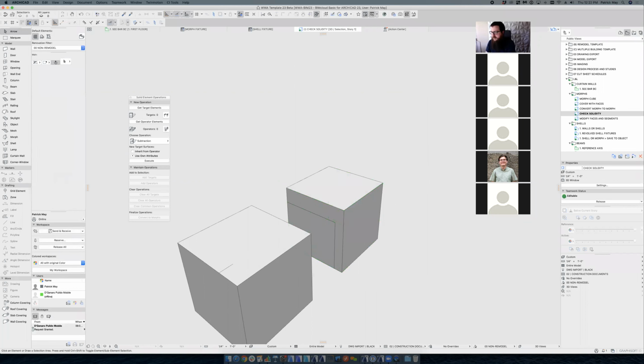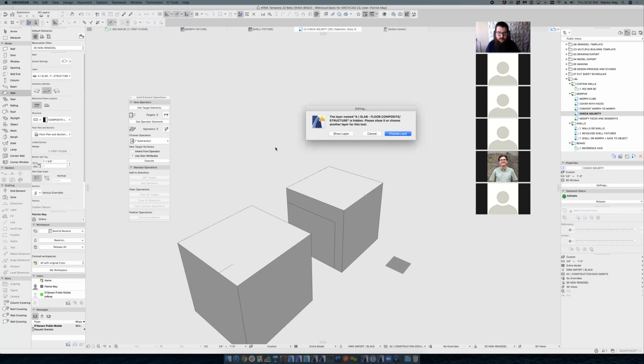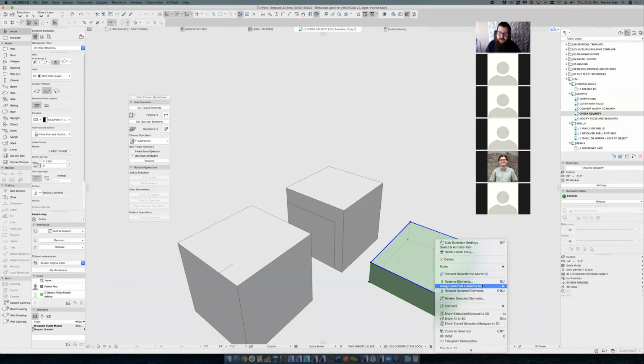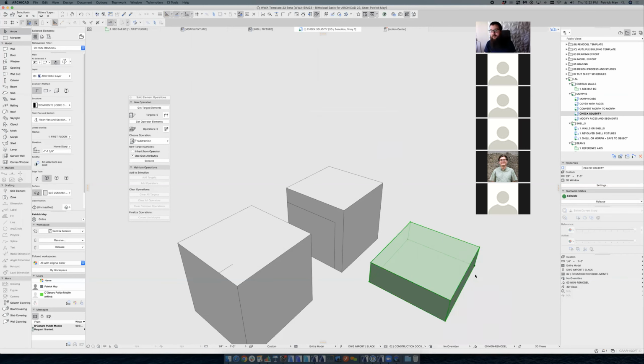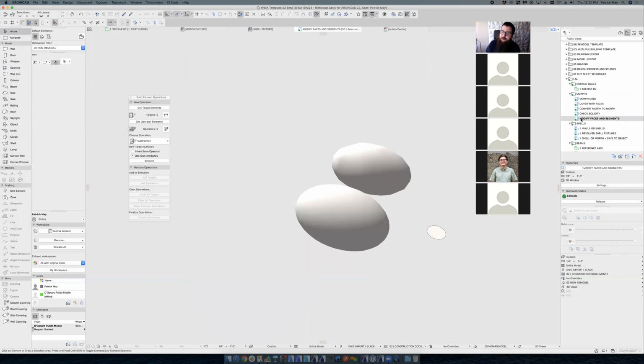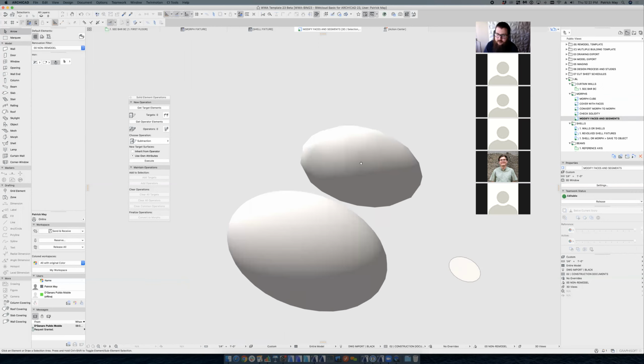So yeah, the morph is not a foolproof tool. It's kind of buggy and odd, and that's all the more reason that it's usually better, if you're modeling a cabinet for example, to just model it with basic massing. We actually have beam profiles specifically to get cabinet massing in there, and then you get to the level of detail you want and you convert those to morphs, and then you can add extra detail after that. Got it. Okay. Thanks.